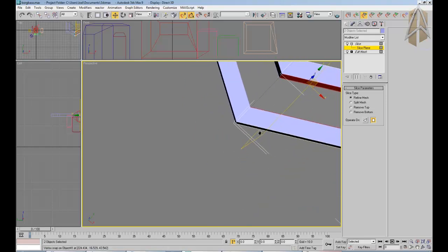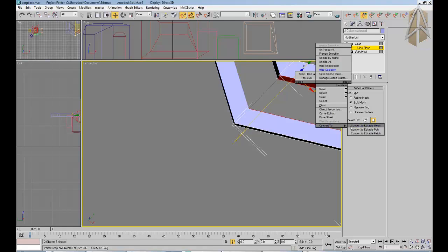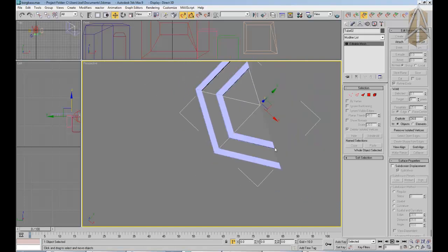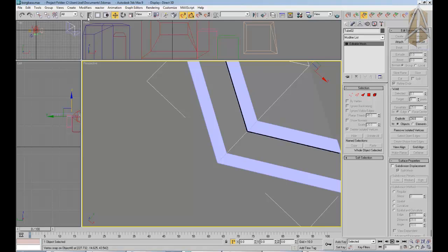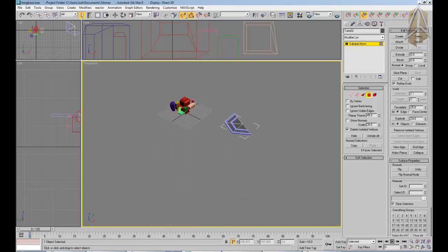Now in order to get rid of this modifying queue up there on the right, I simply use right click and reconvert those 2 polygons into editable meshes. As you see, there's 2 new polygons in here. Now these polygons can be deleted, but they actually don't really need to be deleted, as the new connection we're going to establish between those 2 rings is going to be a separate object anyway.